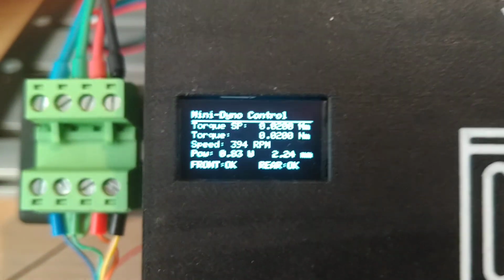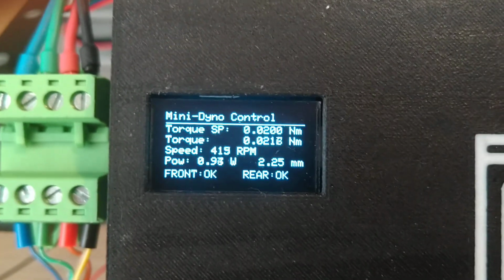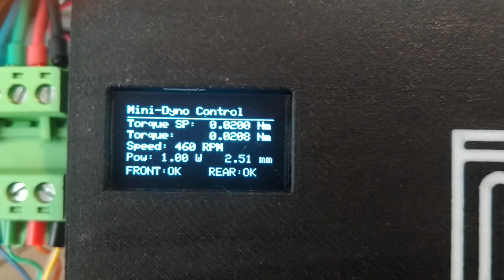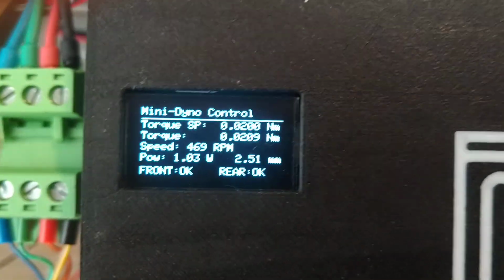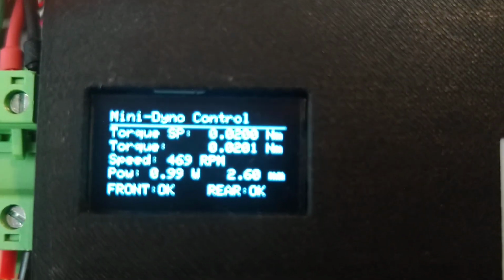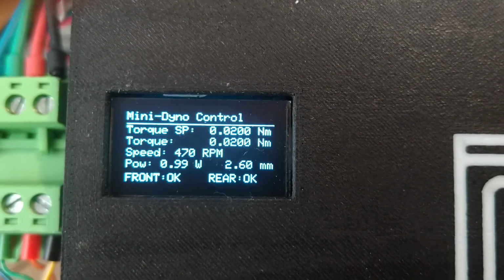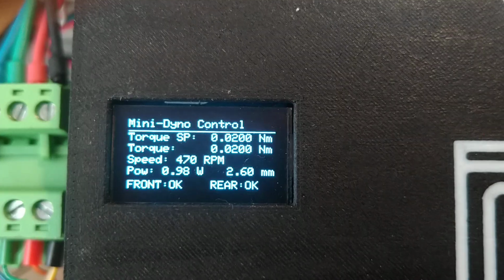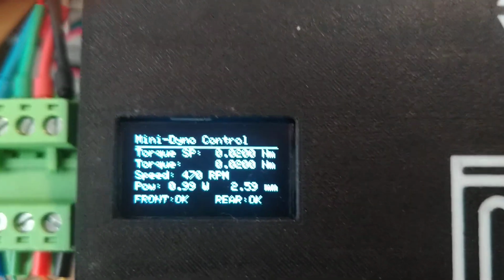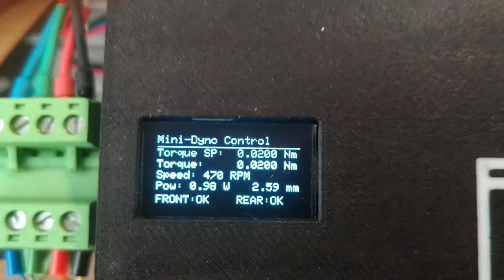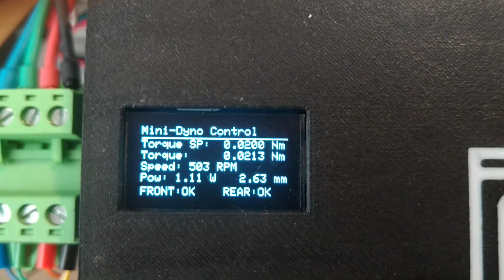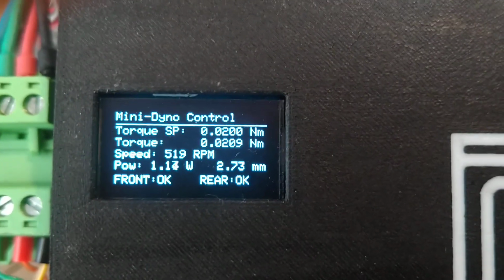So now let's just keep pushing the speed faster and faster, and let's see how quickly the system can actually adjust. And it is adjusting very quick indeed. We are now at 470 RPM, and we are still at 200 Newton meters, and I can actually keep ramping up the speed while the gap is going to be essentially tracking the increase in speed.